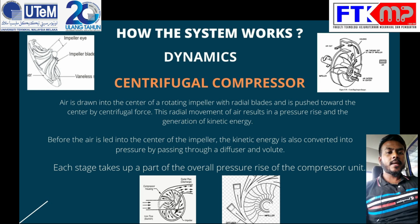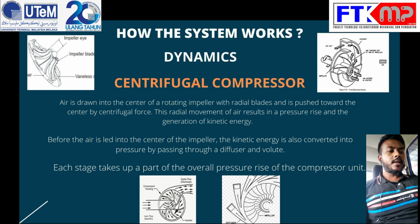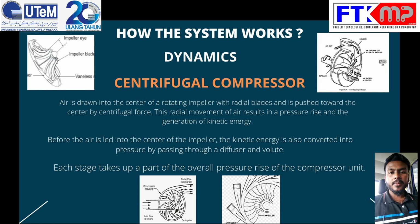And then we go for the second operation. The second operation is that after the air leaves the impeller, the kinetic energy is converted into pressure by passing through a diffuser and volute. And then we go for the third operation. The third operation is that each stage takes up a part of the overall pressure rise of the compressor unit. I stop my topic here.